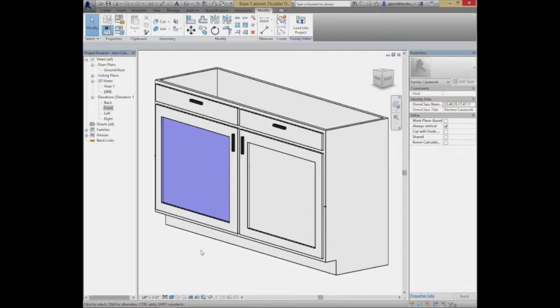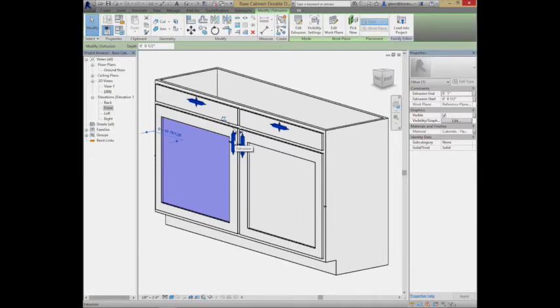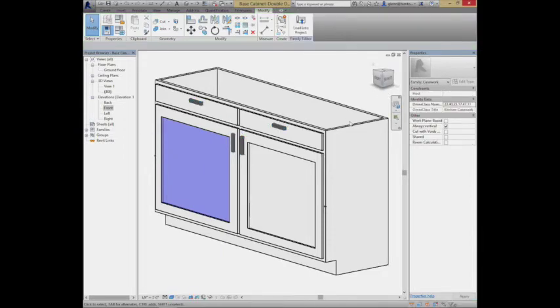Okay, and how you do that is as follows. When I choose those, you'll see there's actually a choice right here of whether or not they should be visible. That seems kind of strange. Why would you make it not visible? But if you want to have something that can or cannot be a feature that can be turned on and off, we can control that. By default, it's set to visible. If I turn it off, they're kind of grayed out right now. As in, when I load that into my project, it won't be visible. But it leaves them there just to show me that they do exist. They're just hiding in this invisible form right now. So that's not too bad.